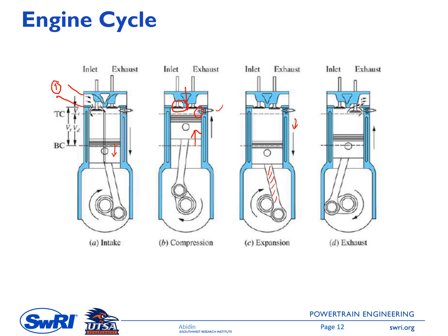Because the cylinder pressure is much higher than the pressure at the exhaust manifold, although the piston moved down, which means the cylinder volume increases, there will be gas exiting the chamber because of the pressure difference. This process is called exhaust blow down.